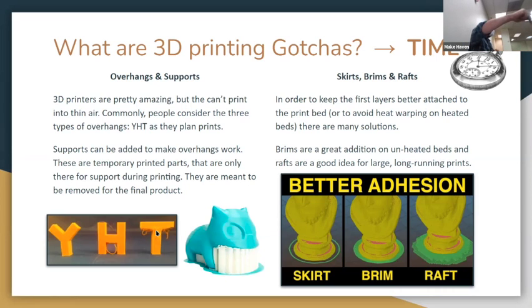And so it'll ooze out plastic, but it doesn't have anything to sit on. And so it comes out really poorly. If you do it upside down, it comes out great. So there's totally lots of things to choosing your design so that they're going to be printable, where you may not design it to be printed the right side up, the way that you intend to use it. So there's some cool things that you can do to your designs there.